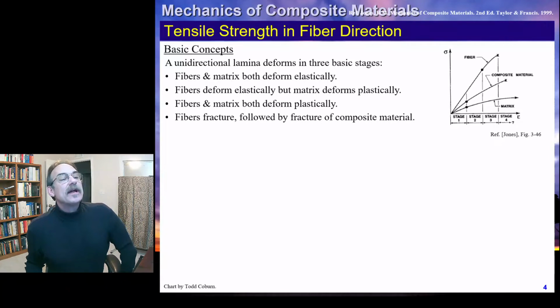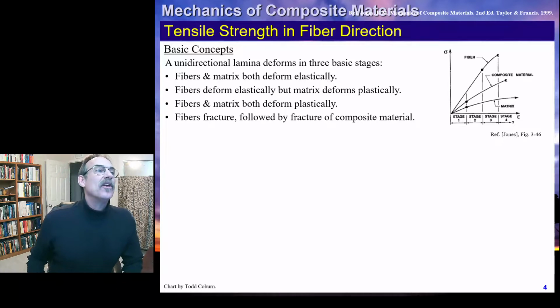Here we see the stress-strain curve for the composite. We see the composite material, that's that middlemost graph. We see that it consists of fiber, which would have reacted like we see here, the upper curve, and matrix, which by itself would act like the lower curve.